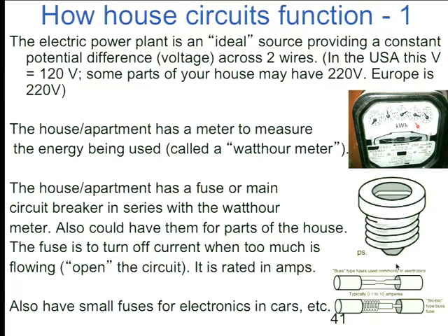That is not what you pay for, you see, because it doesn't matter how fast you use the energy, it's how much you use. So it's not how much you use per time, it's also how much time do you use it, how long do you leave the lights on. If you leave the lights on, you're using power at a certain rate. But what they really care about is over what time do you use it. So what they charge you for is energy, which is the power that you're using times the time you use it. So the unit is watts times time, often in hours, so watt hour. And in fact, you use so much that it's thousands of watt hours. So the unit that is commonly on the bills is kilowatt hours. That's what they charge you for. Roughly it's about 10 cents a kilowatt hour.